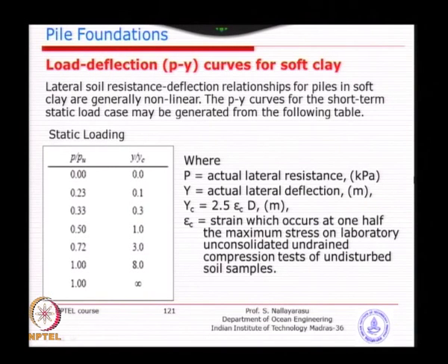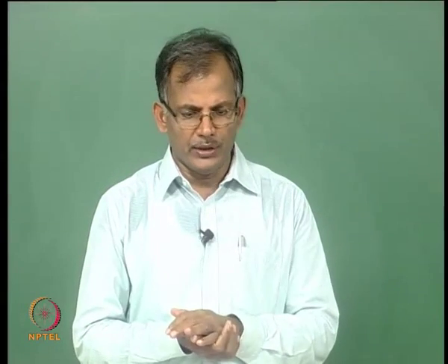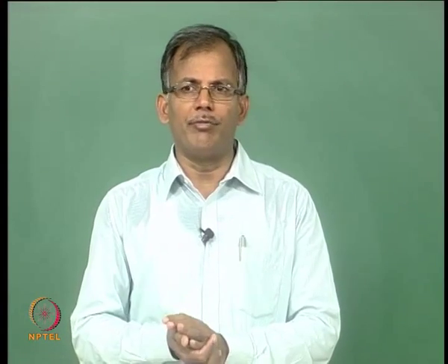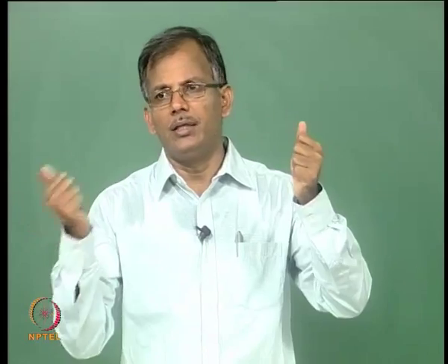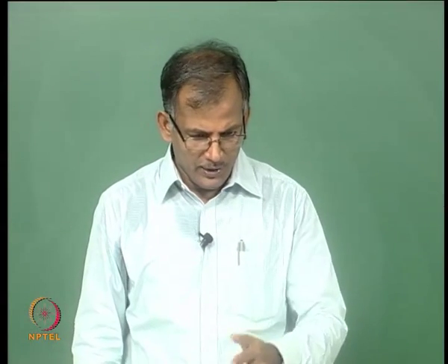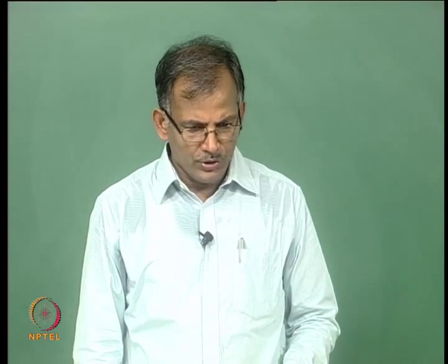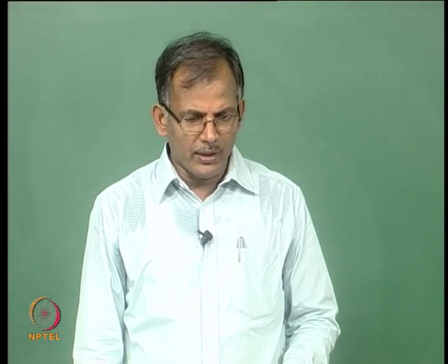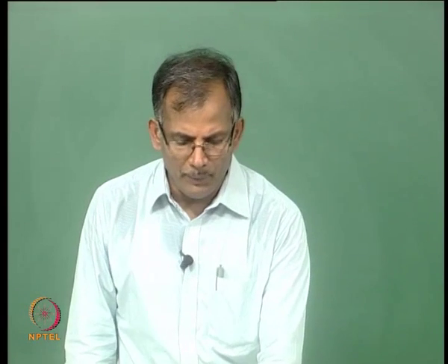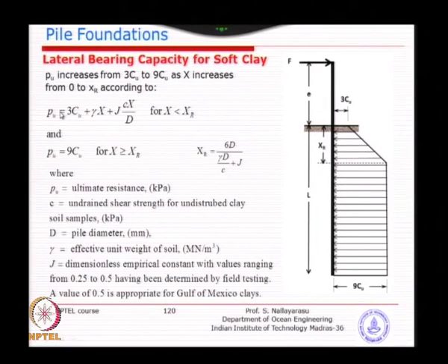And when you want to look at the load displacement graph, it is very similar to what we were learning about T-z or Q-z. Here also you will have the coordinates of the strength point as well as the displacement point, but here in terms of ratios: P is the actual lateral capacity, Pu is the ultimate capacity which you have calculated using this formula, very similar to T-z.